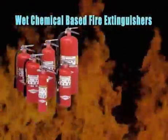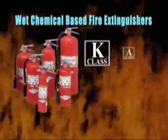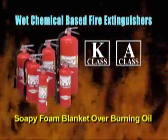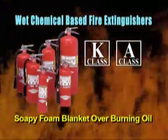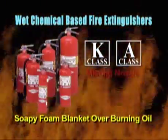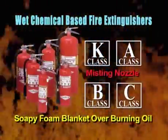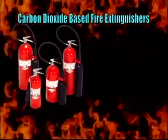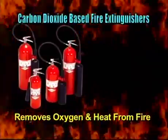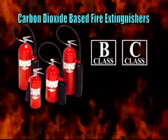Wet chemical extinguishers were developed specifically for use on Class K fires and can also be used on Class A fires. They extinguish the fire by forming a soapy foam blanket over the burning oil and by cooling the oil below its ignition temperature. Some extinguishers are fitted with a misting nozzle, allowing them to also be used for Class B and C fires. Carbon dioxide-based extinguishers remove the oxygen from the fire and also remove heat with a cold discharge. They can be used on Class B and C fires.